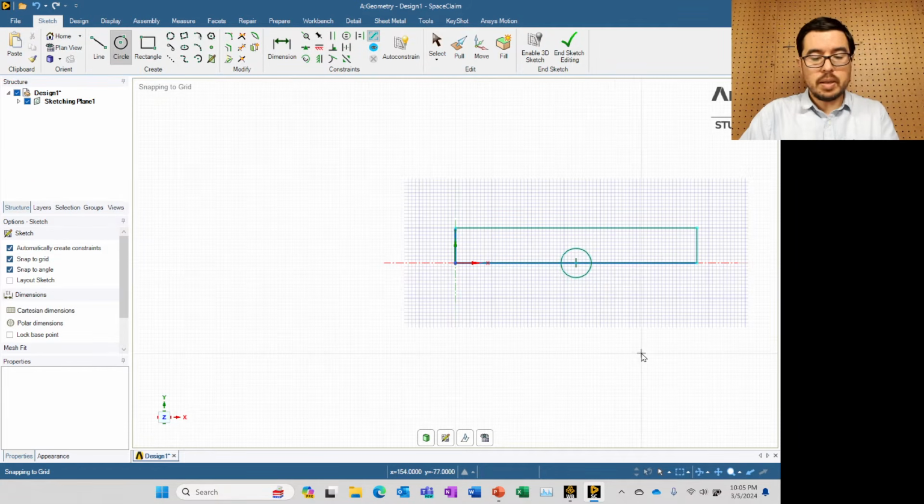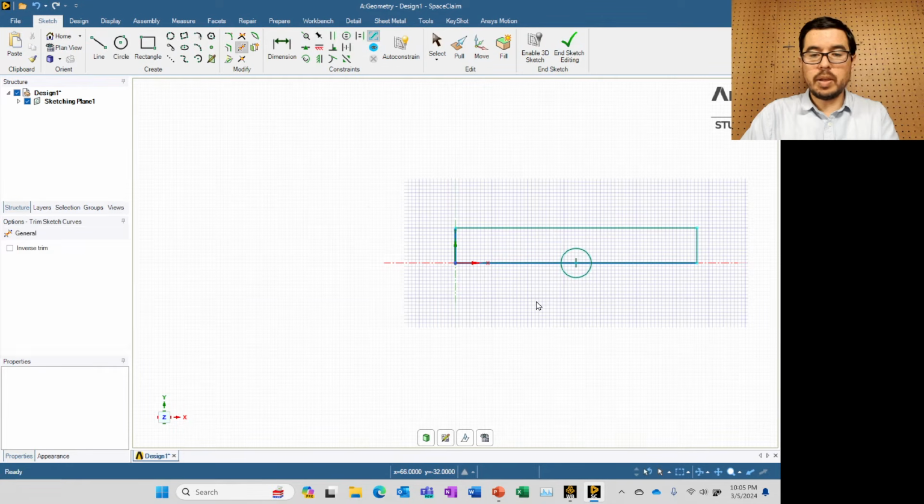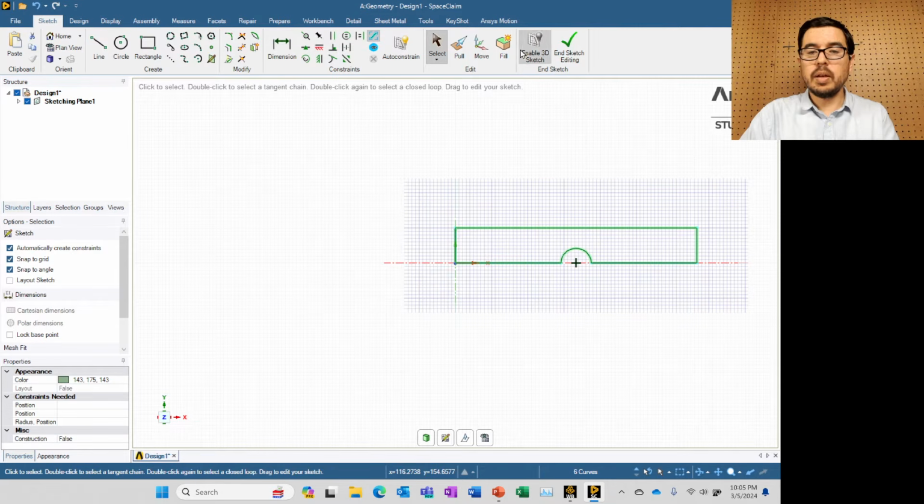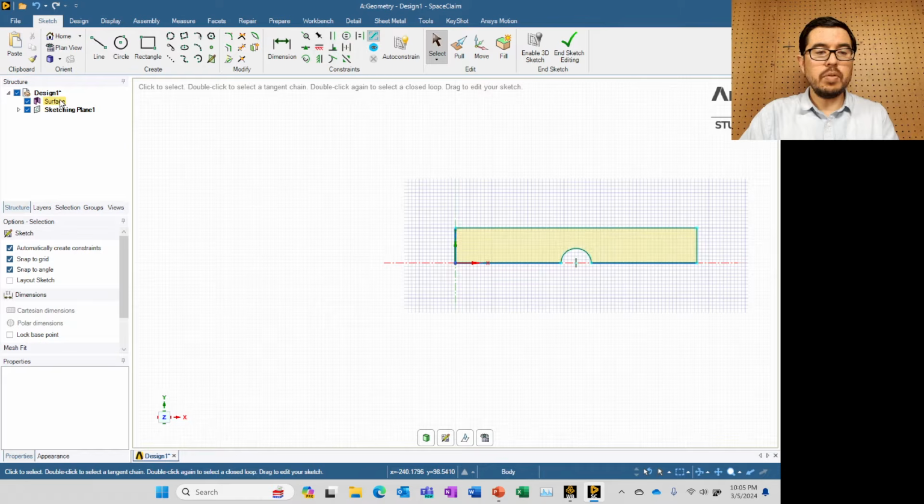And we can click T, or we can click on trim away, either way, but if I click T, it selects that tool automatically, and I trim that away, and that geometry looks pretty good. Come over here, hit select, hold down the left button, select here, then come up here and hit fill, and we've now created the surface that we can use for our simulation.